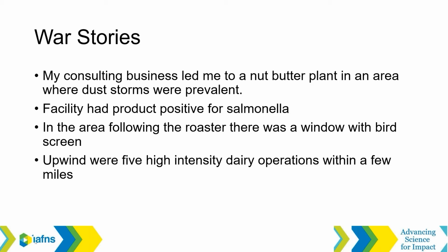My consulting business led me to a nut butter plant in an area where dust storms, I found out, were prevalent. The facility had product positive for salmonella. There was an area following the roaster where there was a window with a bird screen. Upwind, there were 5 high-intensity dairy operations within a few miles. Don't know exactly how far they were away, but they did exist. So, next slide, please.